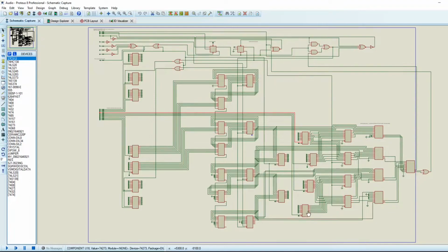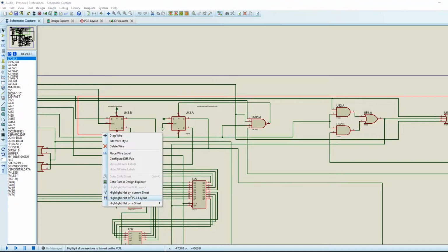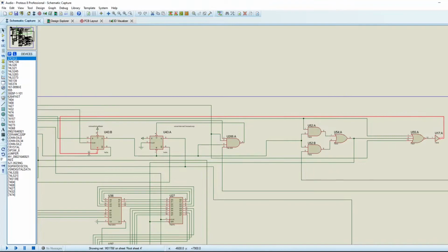So we're taking the loop length or the original sample length, demultiplexing it using the 2-to-1 selectors and then doing a length check. Depending on the results of this length check, it decides whether, if the loop bit is also set, to do the looping logic or to kill the voice active mask. Because if we go back here and highlight, this is the signal which resets the voice active mask.